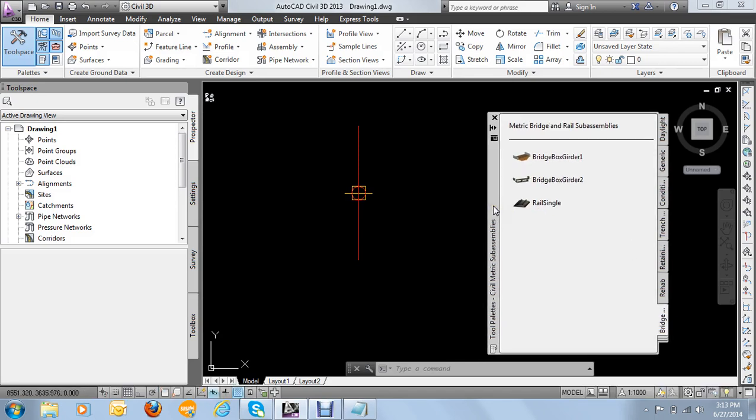Okay, so what I'm going to do, I'm going to create several assemblies, and we're going to see, number one, I will just select the lane and shoulder itself. Another, maybe you can be having lane, shoulder, and ditches, and can create the other with the lane and the curb. So at your own convenient time, you can create several depending on what you want to do.